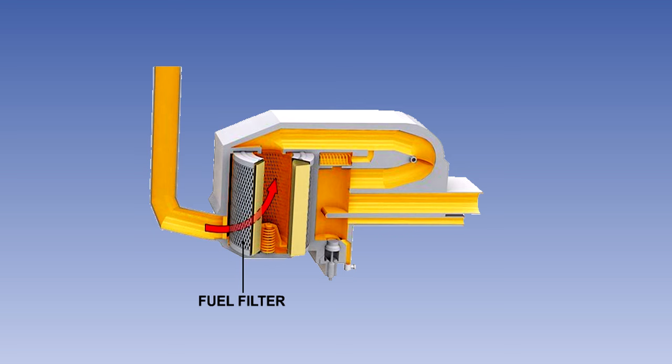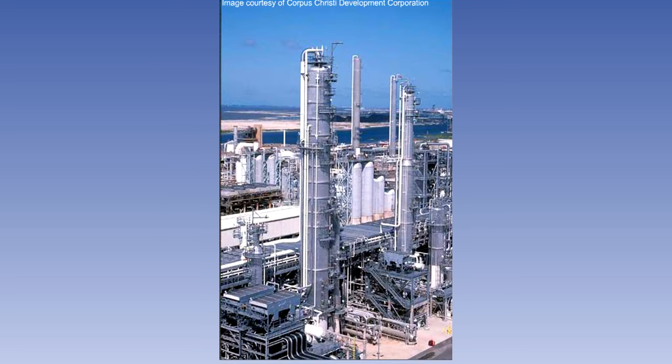The crystals can clog the fuel filter and interfere with the operation of the engine fuel control unit. The effects of waxing can be minimized by the refinery keeping the heavy hydrocarbons in the fuel to a low level.